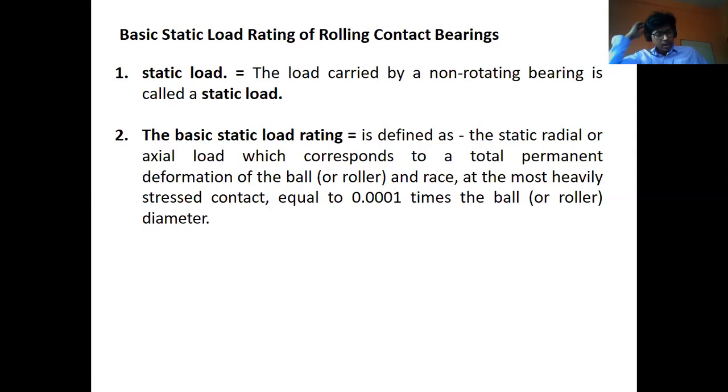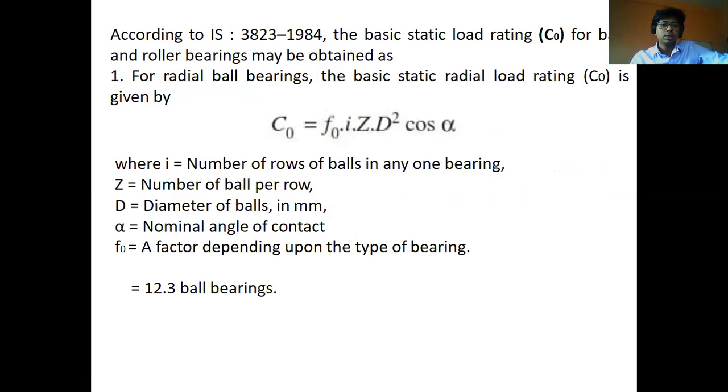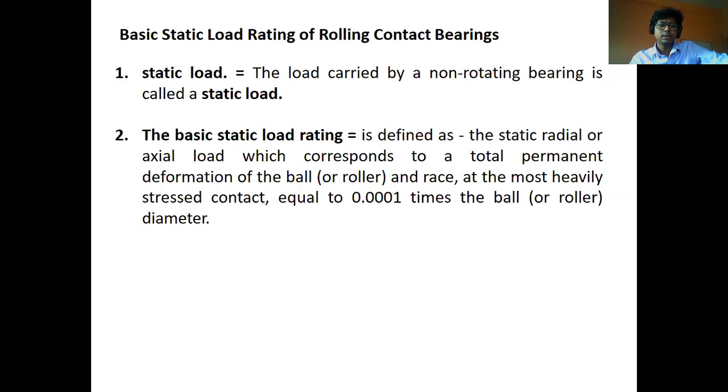Some other terms: reliability is important, in L or L10 depending on the situation. And then the race rotation factor. These terminologies are important, and I'll discuss them later on. Now, basic static load. This is important: C0, the basic static load rating. C0 is an important terminology.